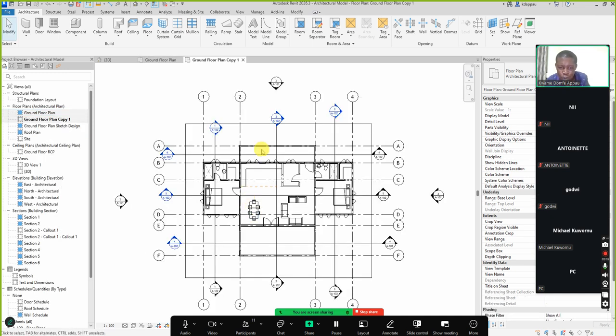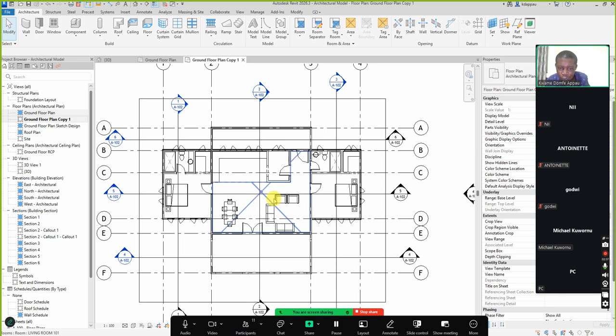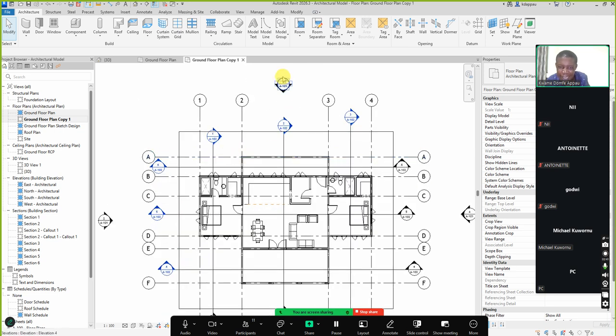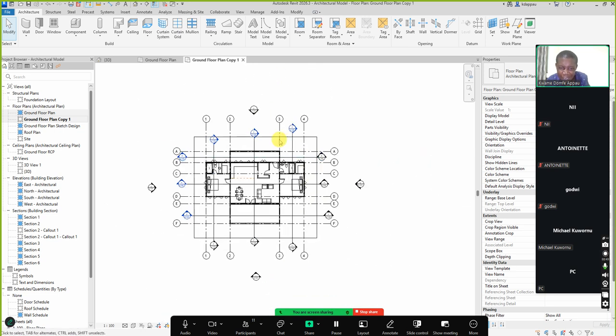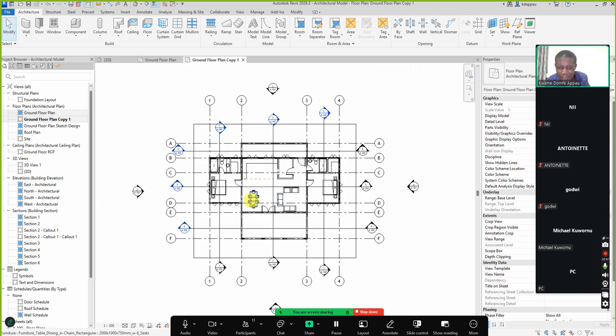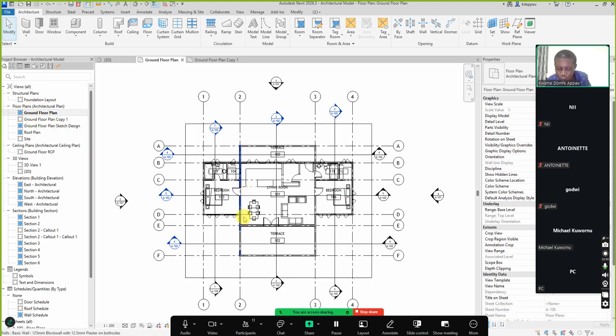Those are annotation elements. So when I choose duplicate, it will only make a duplicate of the 3D objects exclusive of the annotation elements. So you see the view element, the sections, the elevation marker, the grade, and then the model. But you will not see any annotation element. So that you can do a whole new set of annotation within this view without having any influence on the first one.